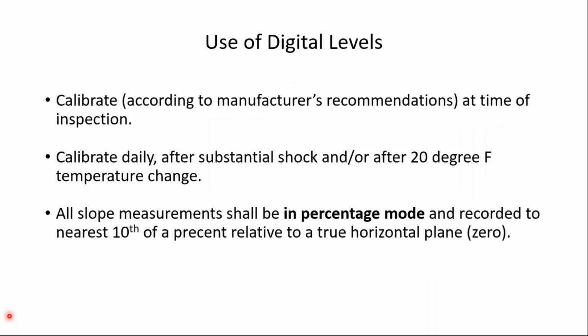In terms of using the levels, be sure to calibrate the level according to the manufacturer's recommendations. At worst, calibrate it daily, but I would actually calibrate it periodically throughout the day, especially if you happen to drop it and it's sustained a substantial shock.